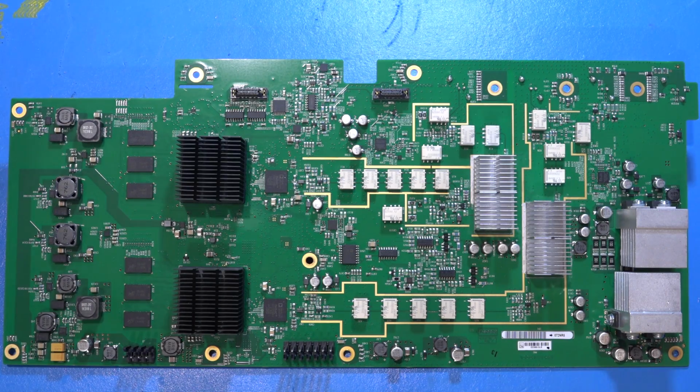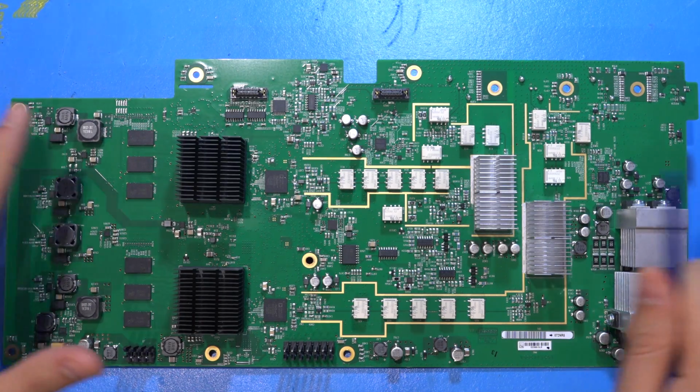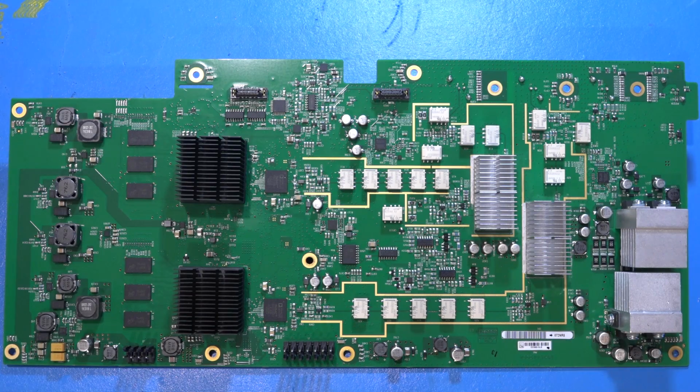Now, this is the main board, and as with any mixed signal board, it's going to have a lot of different components placed in different places, but this is all strategically done in order to maintain good RF performance. So at the very left side, we have a lot of DC-DC converters to produce all the different voltages required for the board to operate, and on the right side we have some more voltage regulation and DC conditioning circuits. As you can see, they're kept as far away from everything else on the board as possible because these are the noisy blocks, and these are the blocks you don't want to interfere with the RF and the analog output.